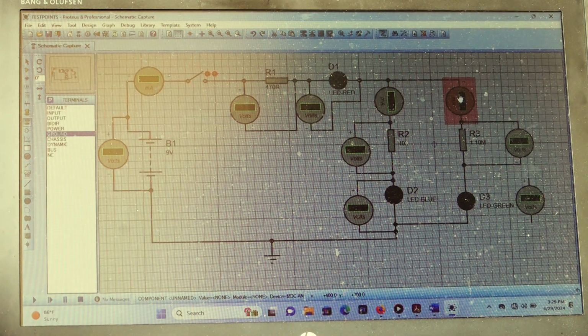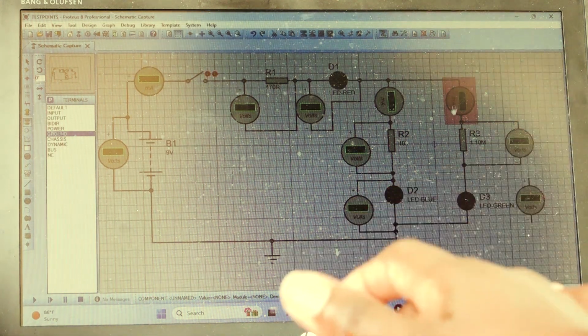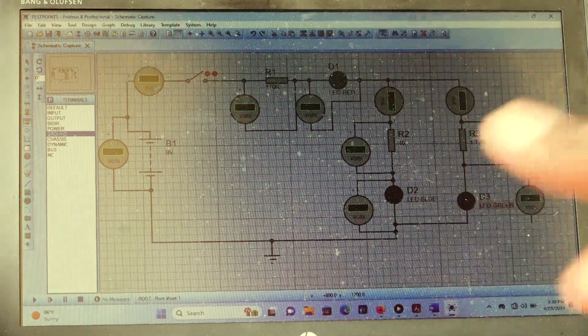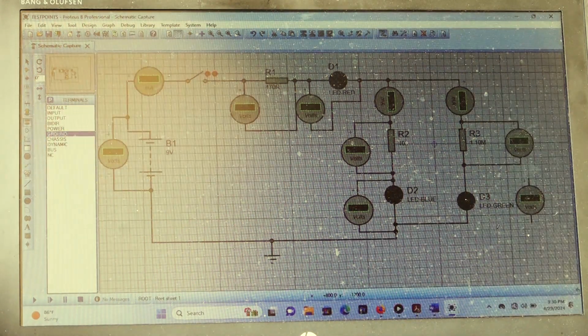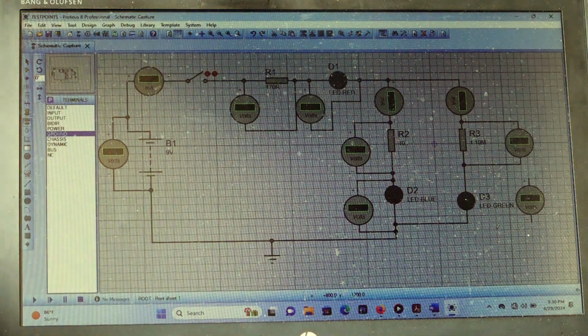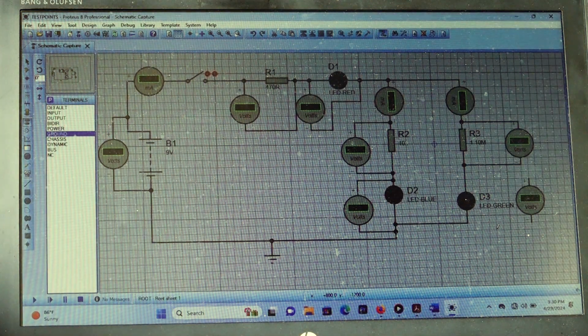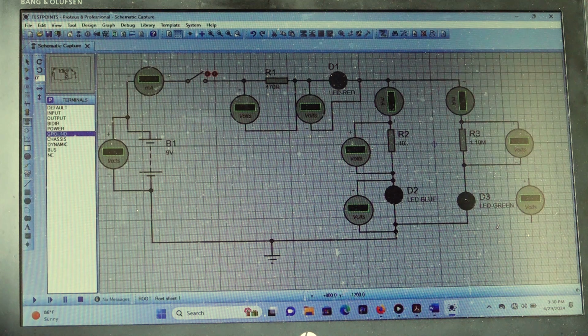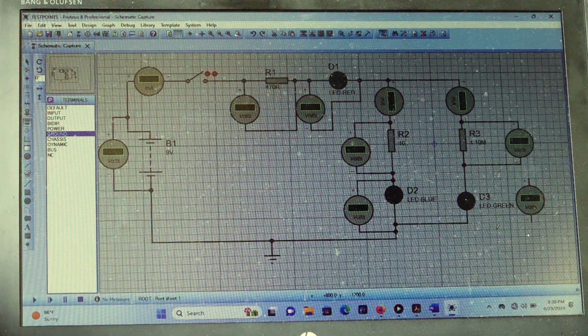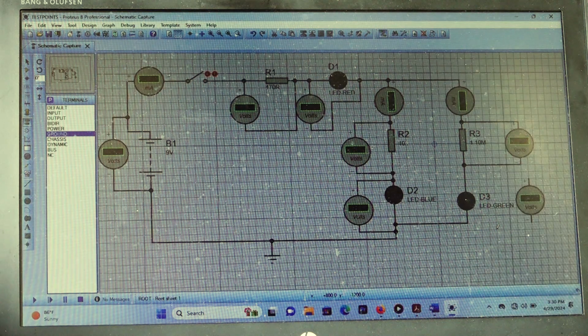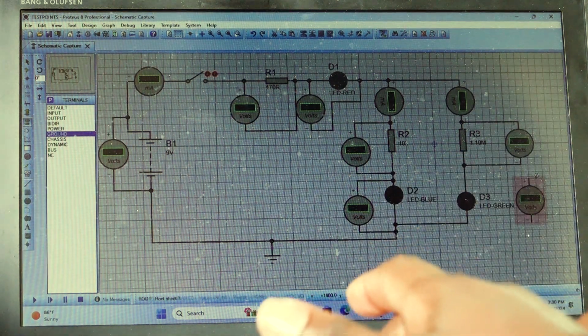Just see the configuration, I've just changed it because, for reasons of the diagram, I've connected them here, downstairs, as I answered in a student's question. Don't care about where you connected the ammeter. What you have to care about is that it's within the correct network. You may connect the milliammeter before a resistor, or in between the resistor and the LED, or after the LED, but within the same network. Are we together, students? Then we are going for the last point here.